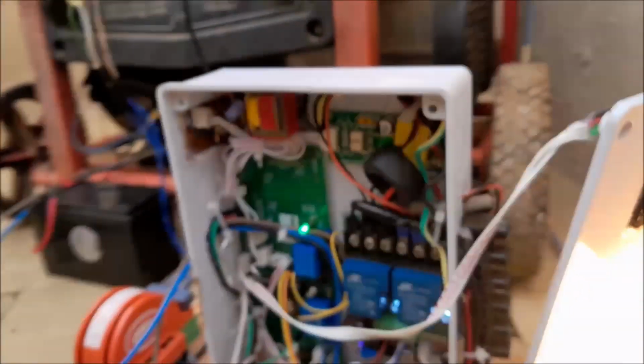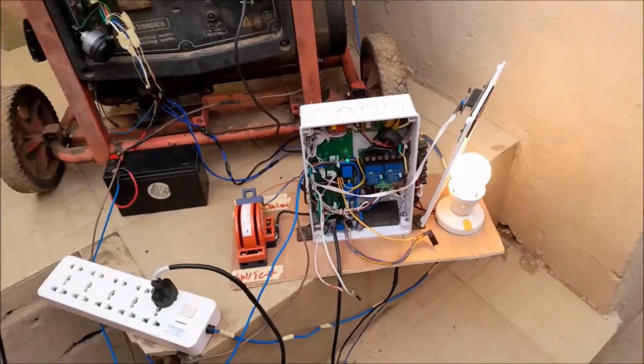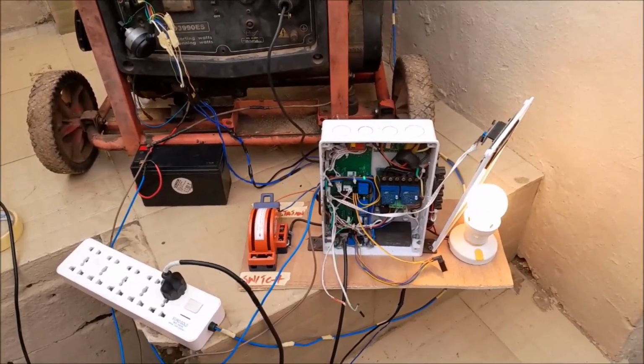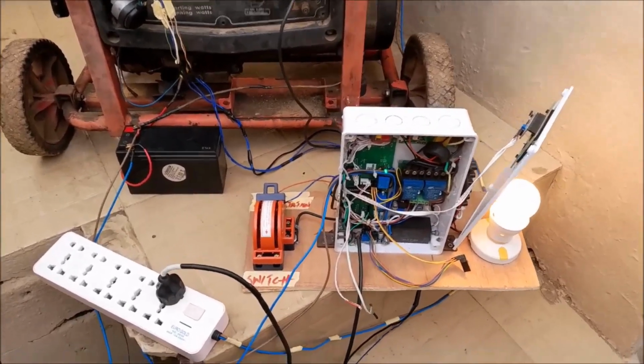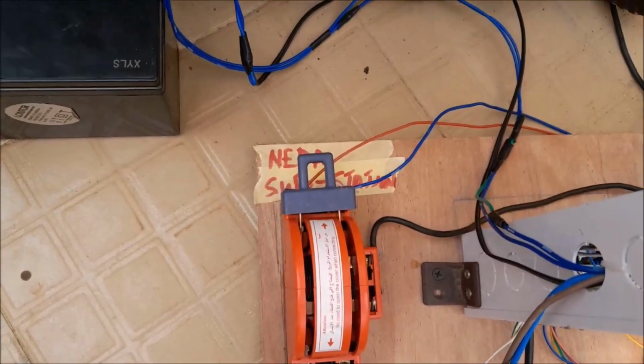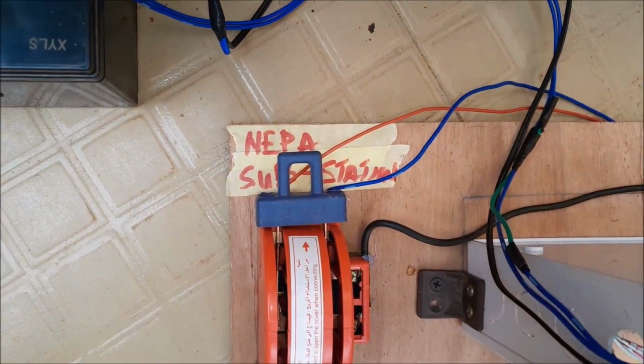During the program testing of the IoT-based automatic changeover switch with AutoGen start and stop, we programmed the design to try starting the generator 4 times sequentially, and if at the 4th time the generator wouldn't start, the design would stop trying but would send an SMS telling the user that starting the generator was unsuccessful and perhaps a technical fault has ensued.